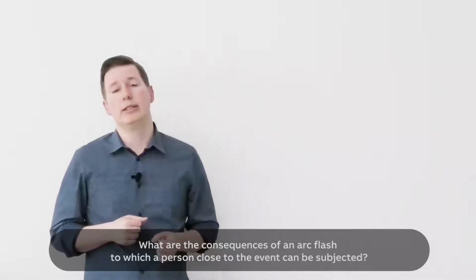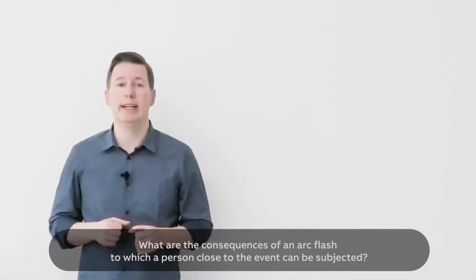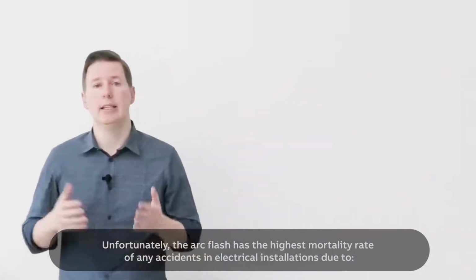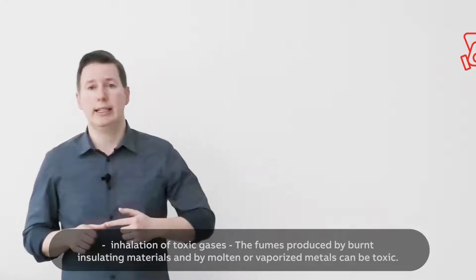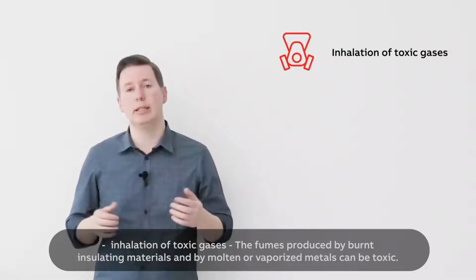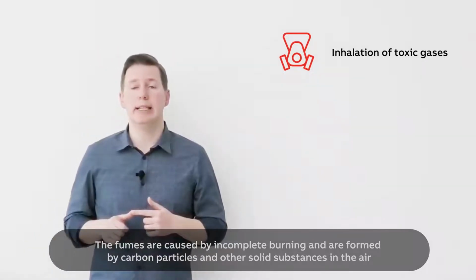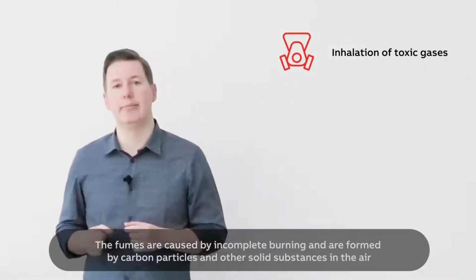What are the consequences of an arc flash to which a person close to the event can be subjected? Unfortunately, the arc flash has the highest mortality rate of any accidents in electrical installations, due to inhalation of toxic gases. The fumes produced by burning insulating materials and by molten and vaporized metals can be toxic. The fumes are caused by incomplete burning and are formed by carbon particles and other solid substances in the air.